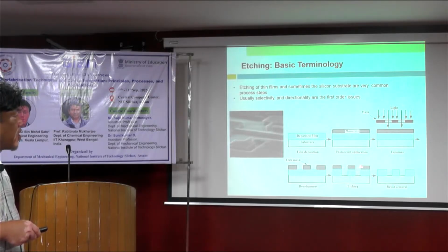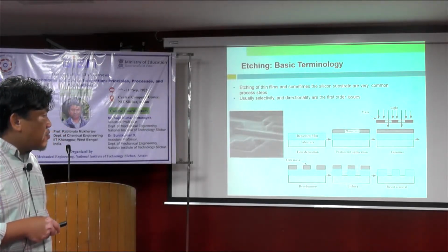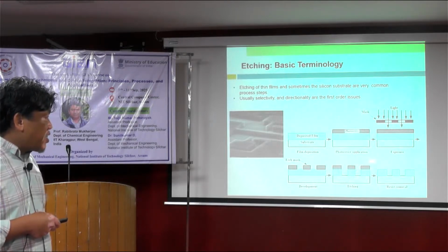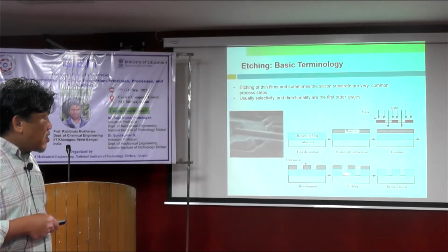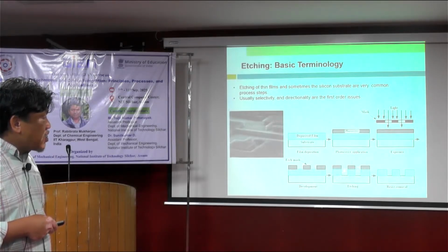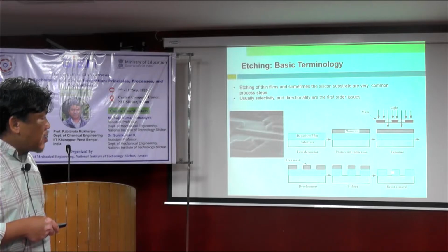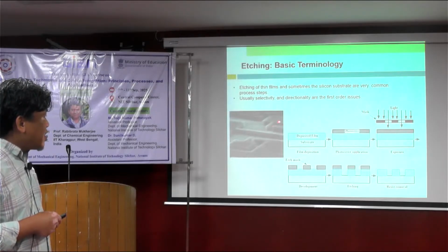If it's metal, for example, you want to have a circuit on this substrate. Then if it's gold, you might use gold etchant. It depends on the materials. Then later on, once it's formed, in this case you might see that it's quite straight. In actual, it might have a different pattern, not that straight. But that is quite normal in the formation using wet etching, or etching in general.